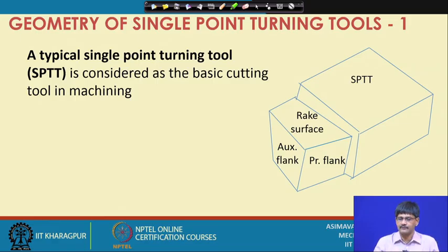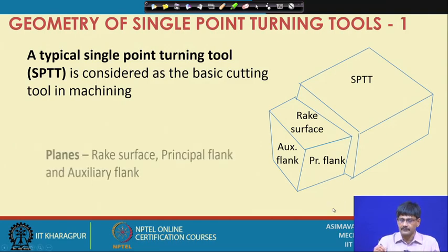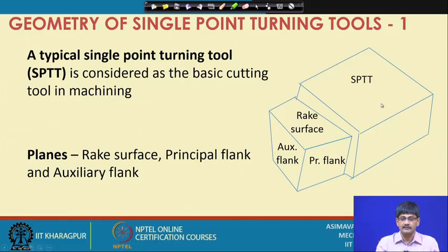On the surface of the turning tool, first of all let us see the back portion of the turning tool. This is the shank or the base or the rear portion of the tool which is held on the machine tool. If we can hold it on the machine tool, it will be securely placed in position with rigidity.